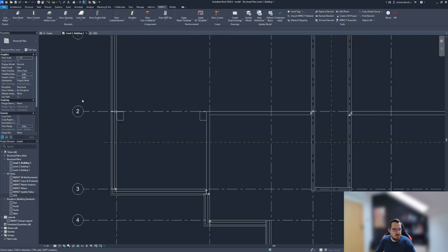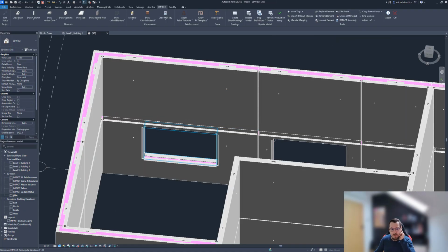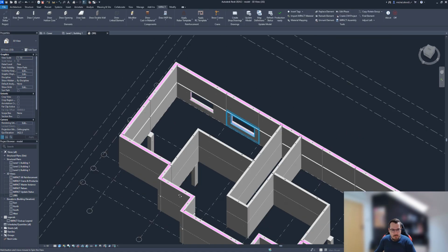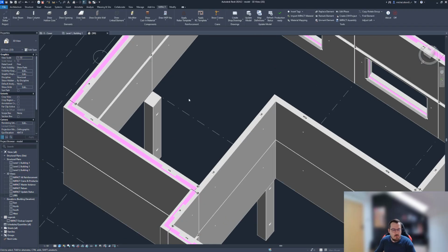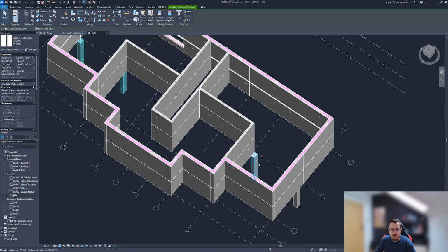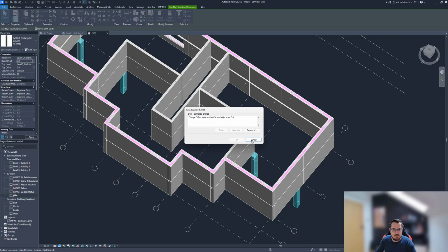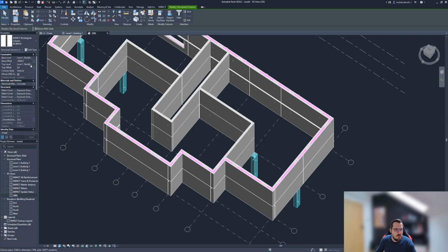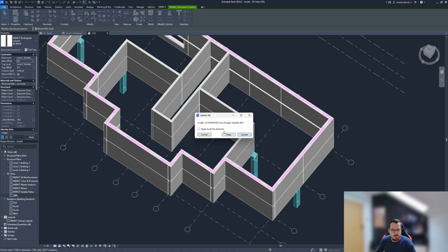Of course, I forgot that in Revit you actually have to place the levels from which you want to operate. Doesn't matter. Let's select all those elements. We'll fix them. Base offset is 0. Top level, cancel. Top is second level, and that's 0. And let's apply. I want to update the lifts. Apply for all elements. Update.